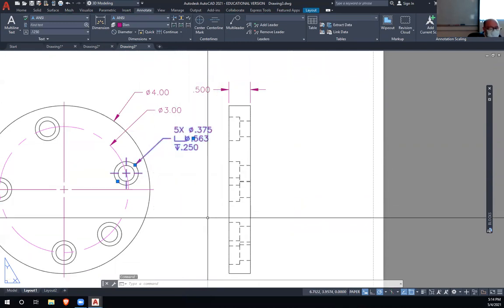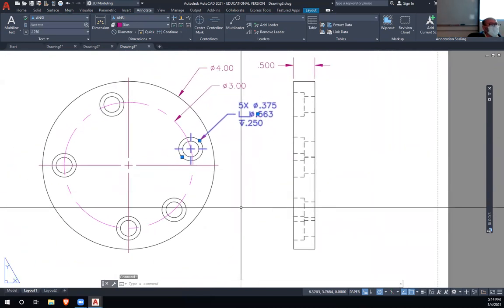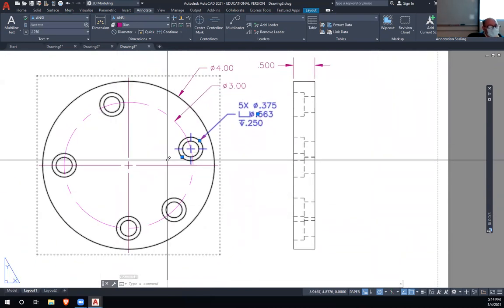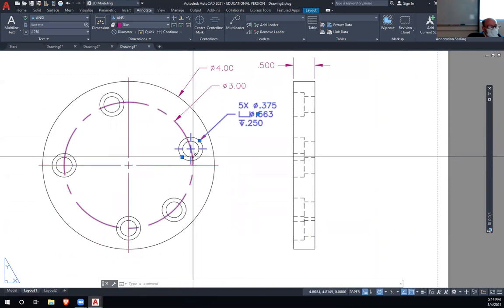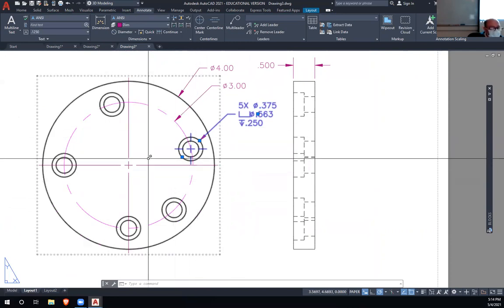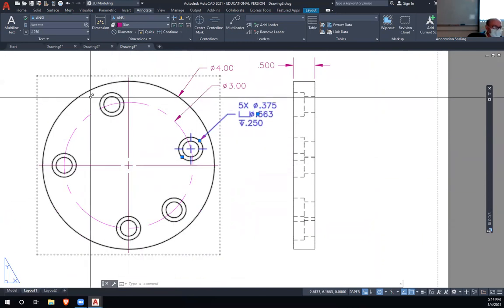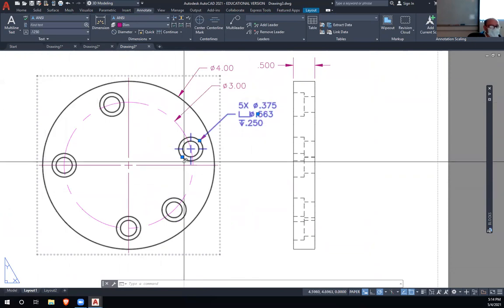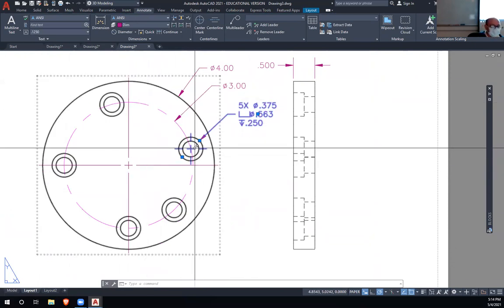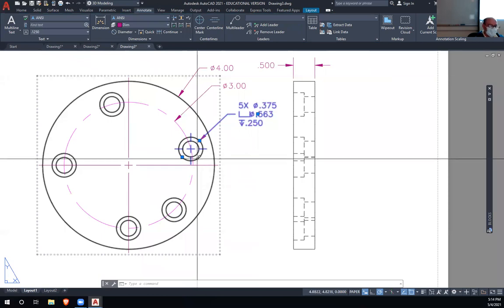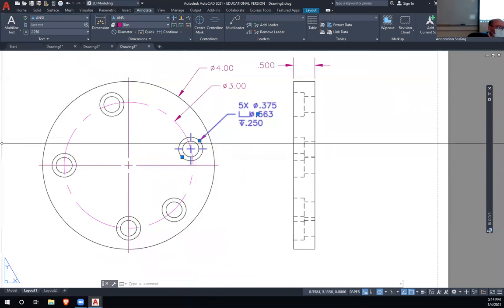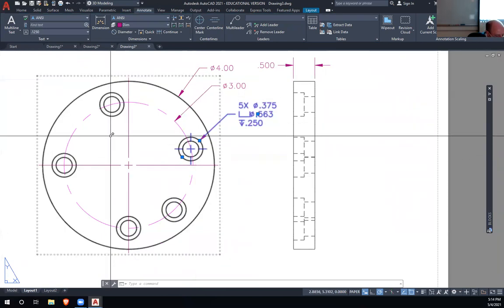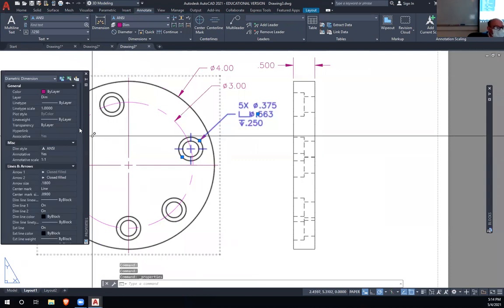Another thing I need to adjust before we're done here is I don't want that center mark in there. That's messing me up, right? I want radial lines coming out from the center of the cover plate here, and I want that to go through there. I don't want this vertical and horizontal thing because that's not it. So let's go to properties.